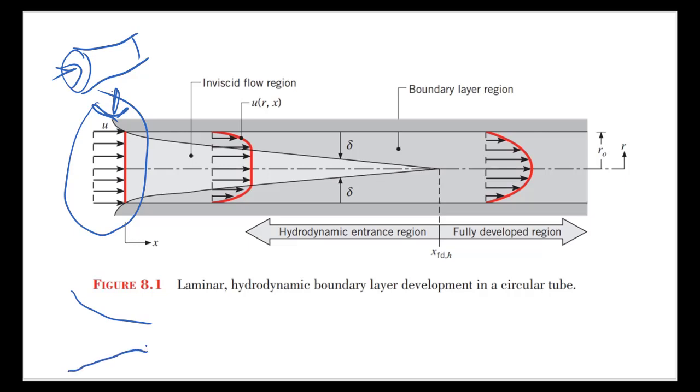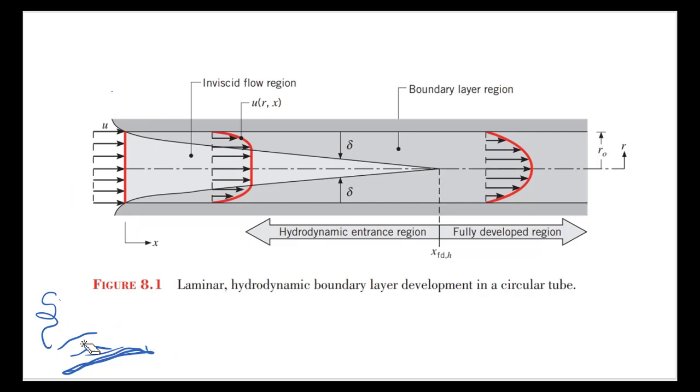a nice rounded inlet. It's not a very nice rounded inlet, but the idea is that as fluid comes in, it could be a little turbulent here, but just before it's entering the pipe that we're considering, it'll have more or less a uniform velocity profile. So that's what we're assuming here. So what we got in this situation is we have a uniform flow coming into the pipe, and right away, once this material sees a wall, the boundary layer is going to start growing.